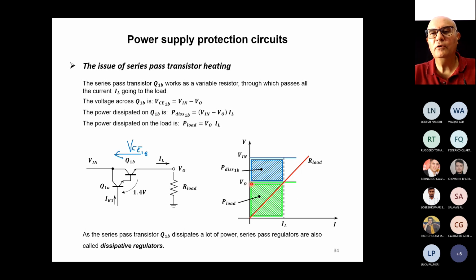But you see that when I work with low voltages, the power dissipated in the transistor increases. This means that the worst situations for such a power supply are those where the power supply is given the lowest voltage. So for a given current, the lower the output voltage, the higher the power dissipated in the transistor. So when I design the circuit, I must take care that the system can sometimes work in strange ways.